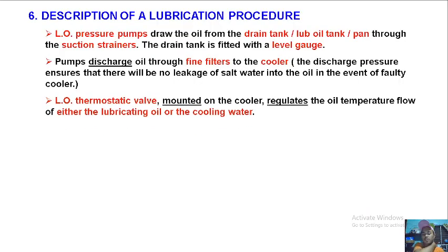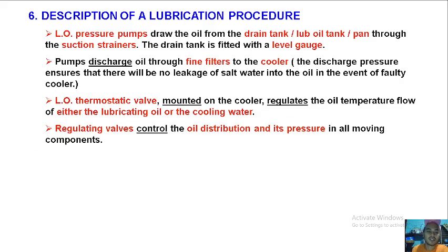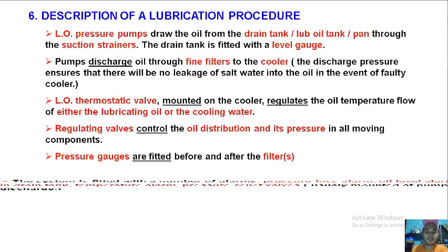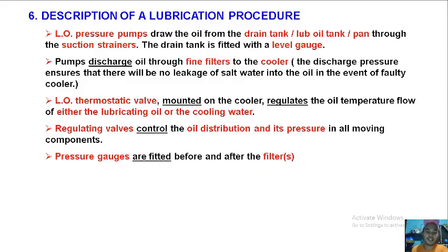The lube oil thermostatic valve mounted on the cooler regulates the oil temperature, controlling the flow of either the lubricating oil or the cooling water. Regulating valves control the oil distribution and its pressure in all moving components, and pressure gauges are fitted before and after the filters so that you can check if the filter is still clean or dirty.